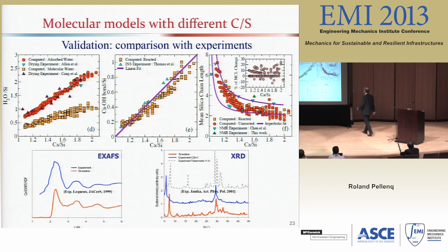There is one more thing to say here. You see that at one given CRS, it looks like you can get different values for the same paste. That brings a new concept, which I think is new in the cement business: CRS is not enough to define everything. What we actually have is what the mineralogists call polymorphs. Same chemistry, but probably different molecular arrangements, and they exist for one given CRS.